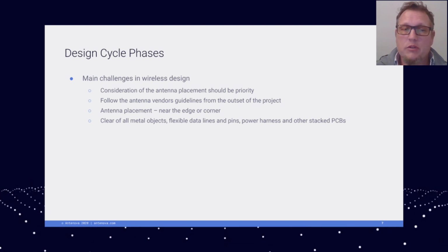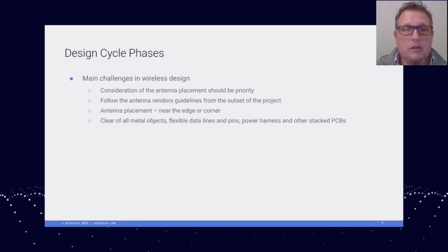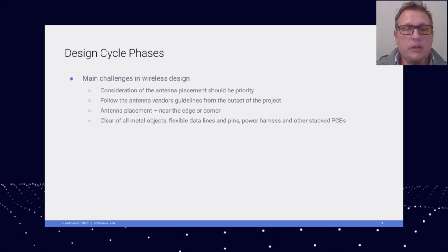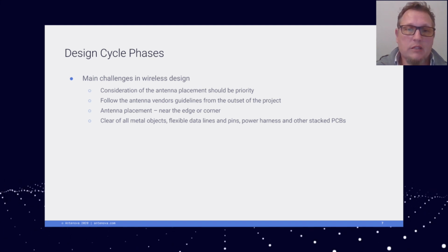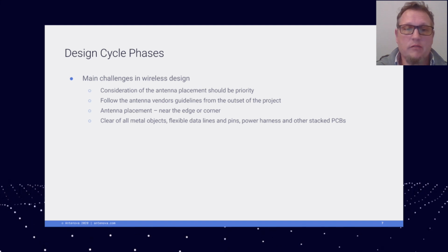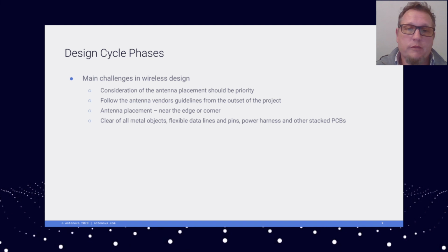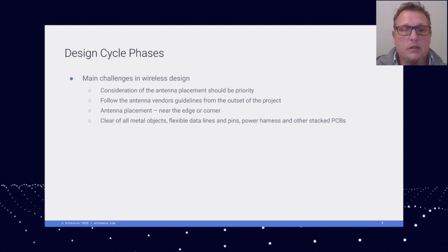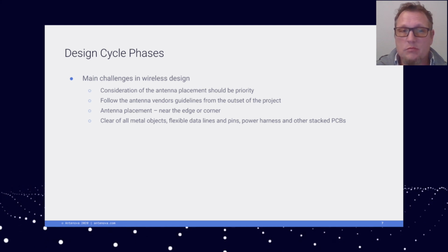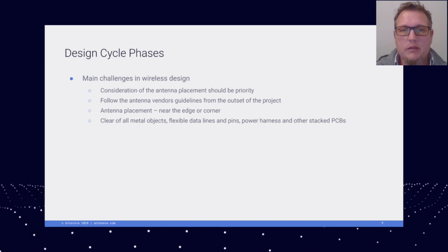The printed circuit boards can get pretty densely populated, so certain antennas can function better along the long edge of the PCB. Others will like to take up the end of the short length of your PCB, and others function fairly well near the corner of your device. So the antenna position is critical, but can be manipulated.